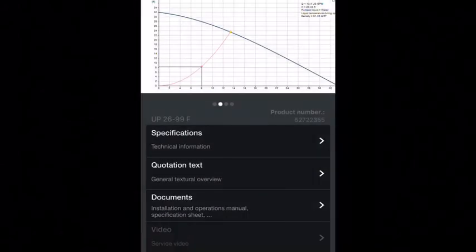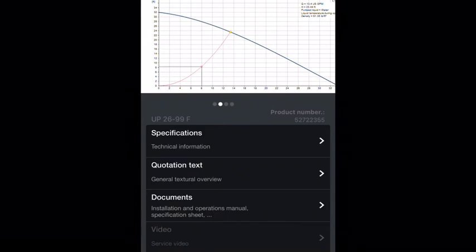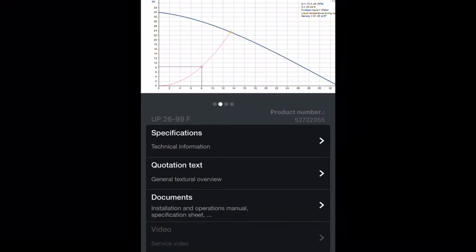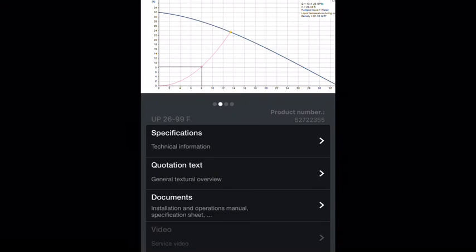All right, so what do we have here? That tells me my flow rate with that 2699F pump would jump up to about 13.4 GPM, and the head would be about 23.44 feet of head based on their app and their calculation, which for most of our service applications, is more than adequate. Whatever accuracy that we can get on there, that's great. But this is a nice, super fast, easy way to do this.